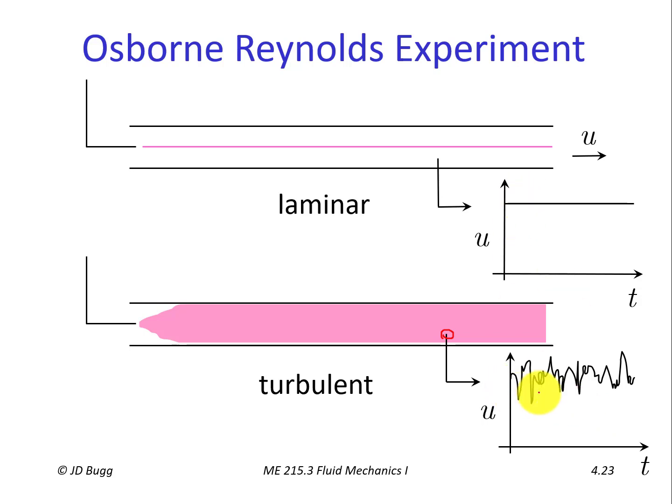Now, realize that if we were to look at the average of these, so the mean value of this velocity, maybe it's there somewhere, it's still a positive number because on average, certainly the fluid is still traveling from left to right here. We have a flow from left to right, but the instantaneous value of that velocity is fluctuating quite wildly around that mean. So this is a characteristic of turbulent flow, fluctuations.